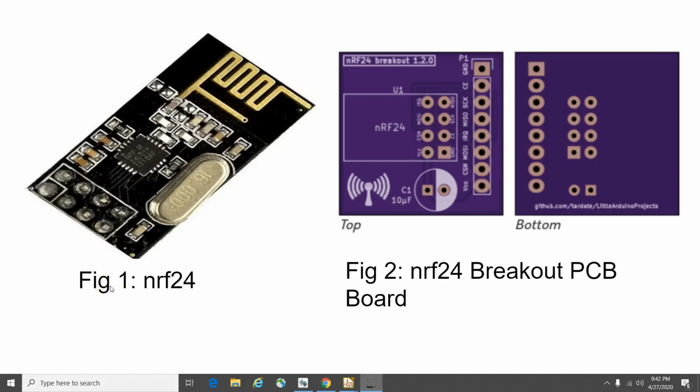Hi everyone. In this lecture, we are going to update the layout and wiring so that we can include the new capacitor in our design. As you can see here on this slide, we have the capacitor of 10 microfarad connected in the PCB board. So we have to create a capacitor in our KiCad schematic. So let's do it.